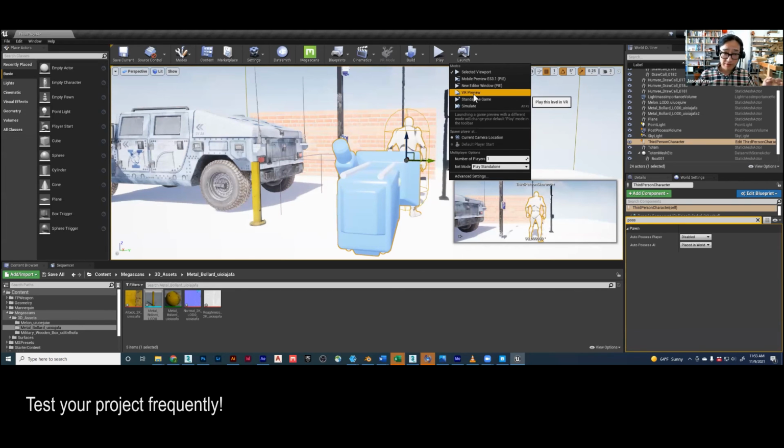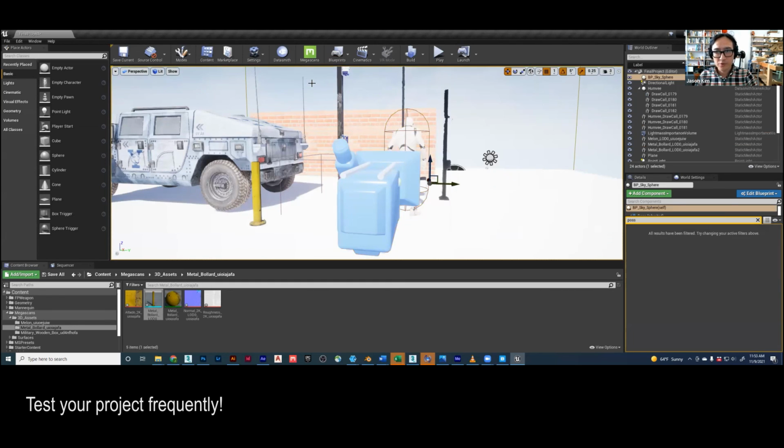Because if you end up with a lot of high polygon assets, it might slow things down. It might cause some delays or little flickerings and things like that on the VR headset, which can lead to some discomfort, some motion sickness and things like that. So we want to make sure our frame rates are pretty good.